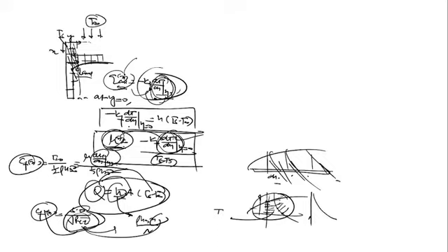They can ask you in the question: if at the wall the fluid is always stagnant, then heat transfer at the wall initiates by conduction, and at the same rate heat transfers in the rest of the fluid by convection. Then what is the need of the convective heat transfer coefficient if I know the temperature distribution at the wall?